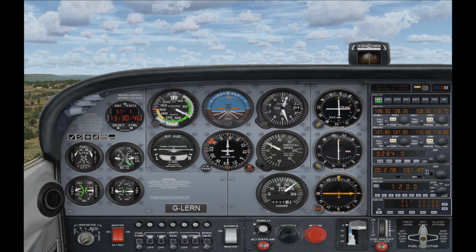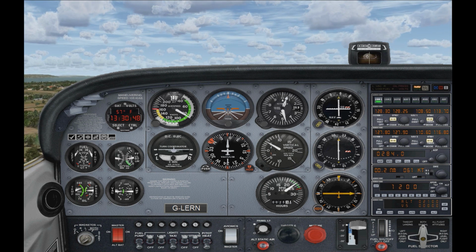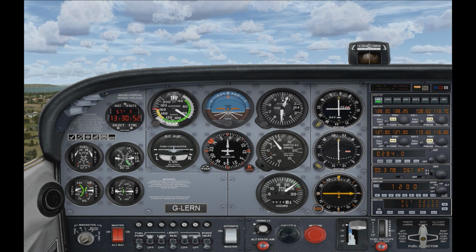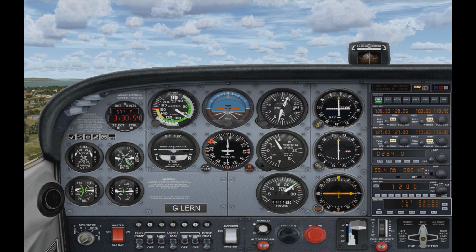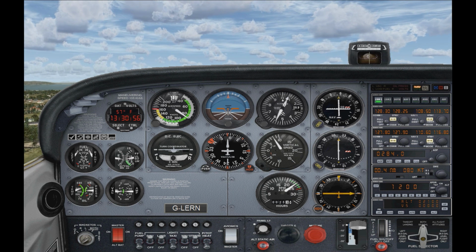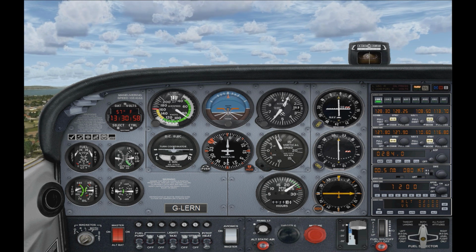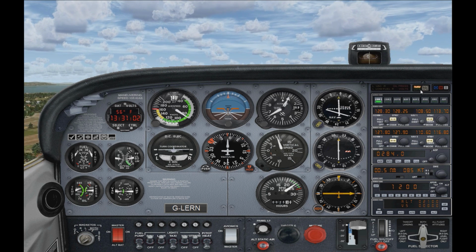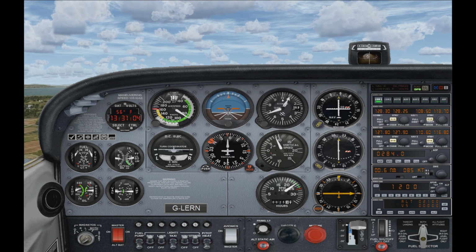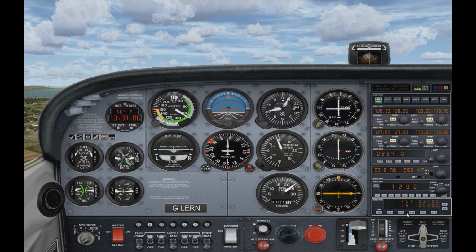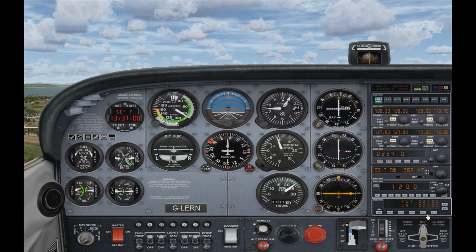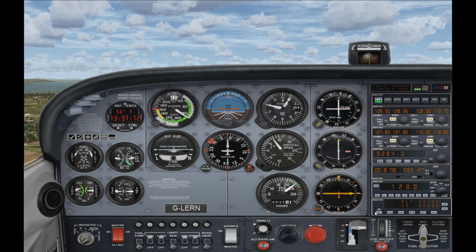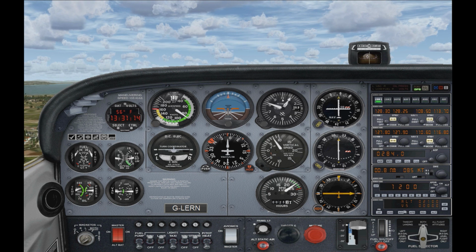And once you're happy that you're heading away from the ground safely. Now, if we wanted to hook into the GPS again to get into that hold, what we need to do first of all is switch our radios back onto GPS. Now, during the approach, I've disabled the autopilot, so the plane is not flying itself. I'm still in control of the plane at the moment.